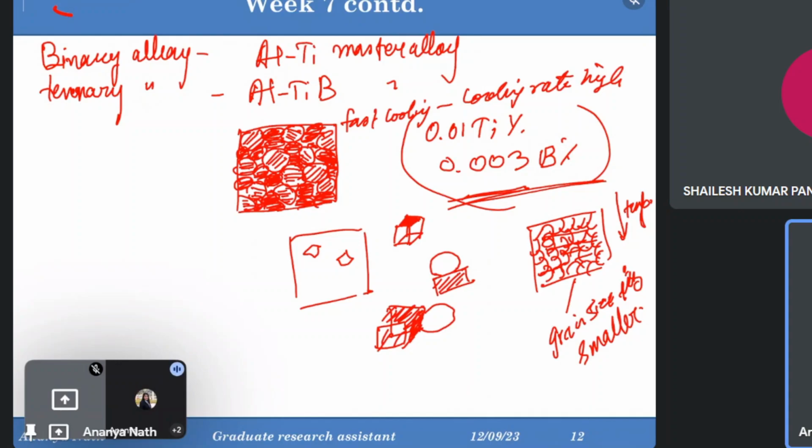What does grain boundary area mean? This is a lattice, and this is another lattice, and the boundary between these two is the grain boundary area. So grain boundary area doesn't mean a particular area having another lattice. It's the boundary between two differently oriented lattices. It's like two atoms in a bond in which the bond length is different from the bond length in each grain, right? So the bond length may be increased, they are more stretched, so the area means that only.